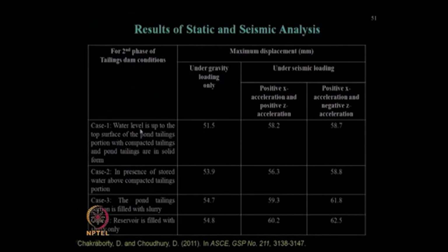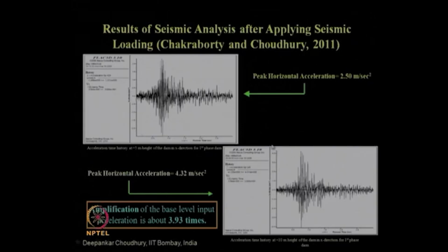Compared to that, output at 10 meter level and at 5 meter level, you got these values, which are given over here. So, it shows clearly an amplification of about 4 times in that material. So, when you are considering your design of slope stability etc., you need to consider this one. Clear? But pseudostatic analysis cannot do that, only pseudodynamic can take care of this amplification.